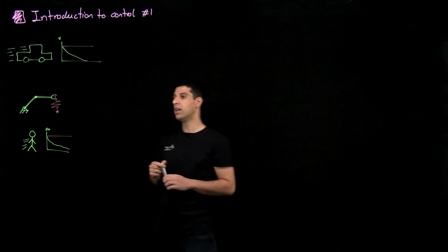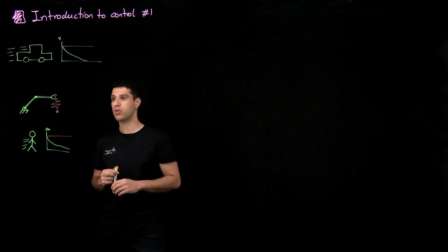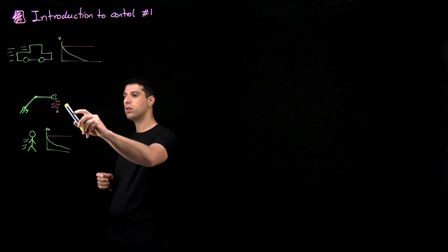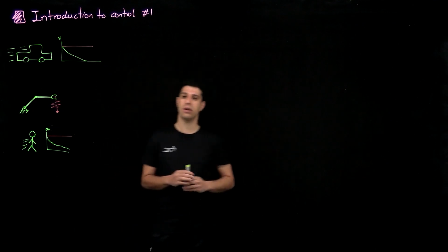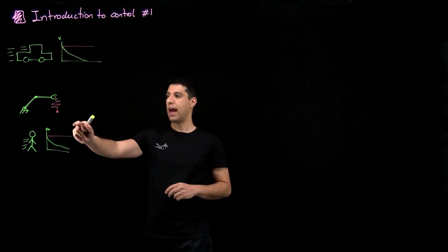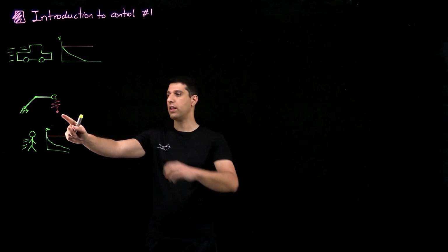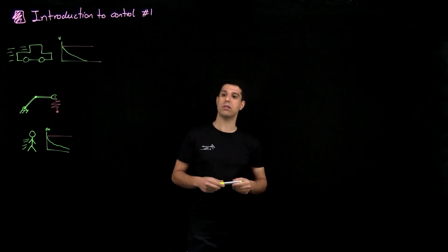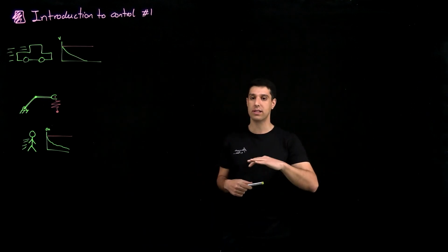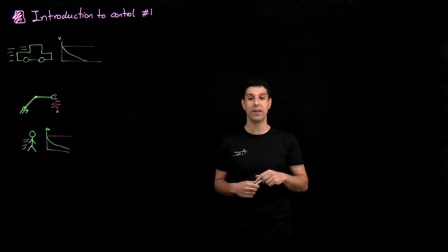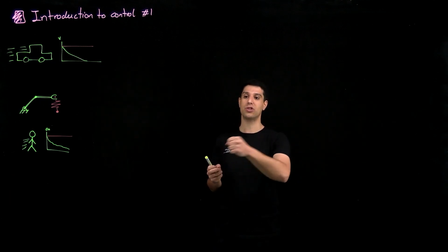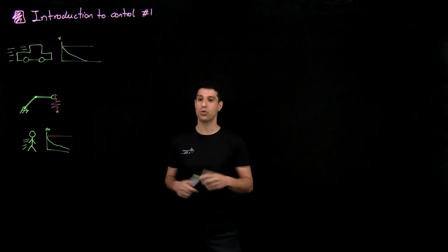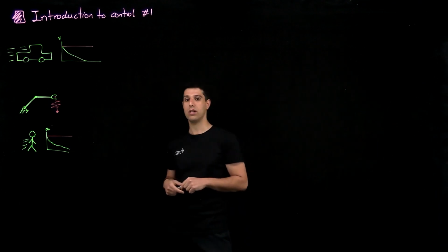So ideally, especially in human-robot interactions and collaborative robots or cobots, you often want your robot to behave compliantly, as if there is a virtual spring, so that when you move your robot around, you don't feel the dynamics of the robot itself, but completely different dynamics, as if you are just interacting, for instance, with a mass spring damper system. So you don't feel the true dynamics of the robot, and hopefully you don't get injured when the robot hits you.